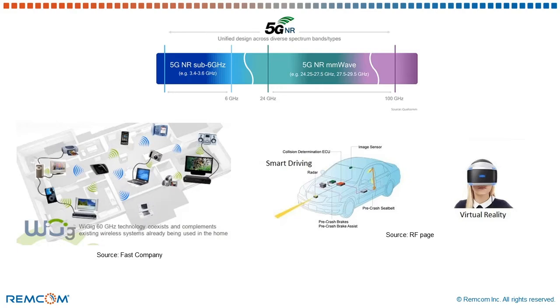The WiGig system operates in the unlicensed 60 GHz band of the radio spectrum, providing a speed of 7 gigabits per second. Due to their small wavelengths, WiGig utilizes antenna arrays along with beam steering to support such high data rate applications. It is therefore a mandatory requirement to design and assess advanced antenna arrays to support ultra-high data rate applications.